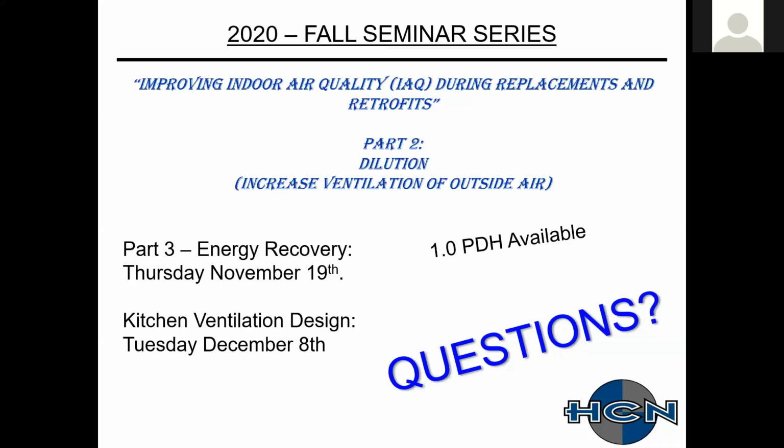If I could chime in, that's all depending on the layout of the type of equipment. So if you're in a bigger built up type packaged unit or chilled water, hot water air handler, it's more appropriate to find a place for the humidifier inside the package system or the built up air handling system. So something small would definitely have to go to the duct.